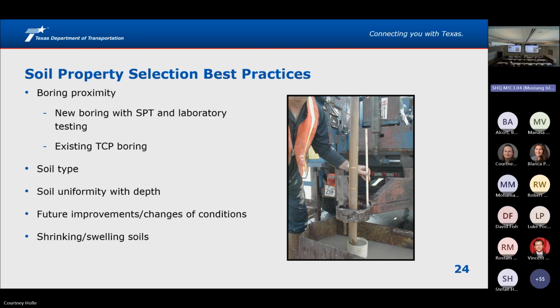How uniform the soil is with depth, as I mentioned, from a laterally loading standpoint, it's not as linear. If the soil strength gets stronger, it might not necessarily affect the length as much, because I'm concerned about top deflections, what controls the design. So having a fairly weak soil layer at the top with something a little bit harder at the bottom doesn't necessarily shorten the shaft, or it's not quite as linear when it comes to the design as axial,